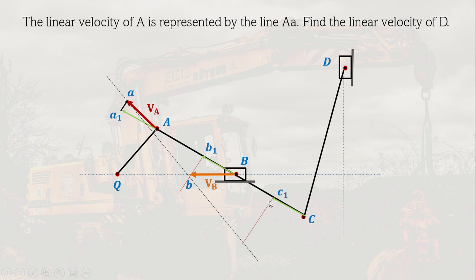So the intersection of that line to this proportional line that's connecting the head of AB is the absolute velocity of C. So we're going to draw an arrow from point C to this intersection. And that is now our velocity of C. So in this method, we were able to obtain the velocity of C. That is one technique that we can use if there are 3 points in the same line. So we can use the proportion.